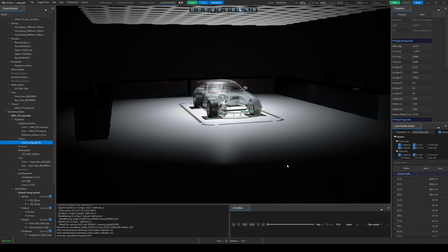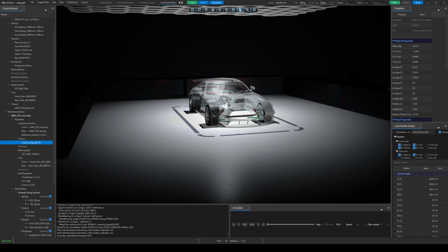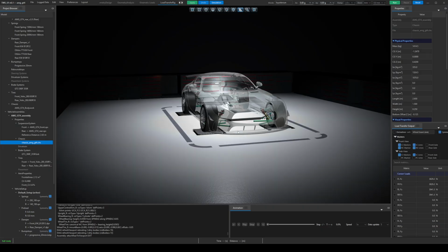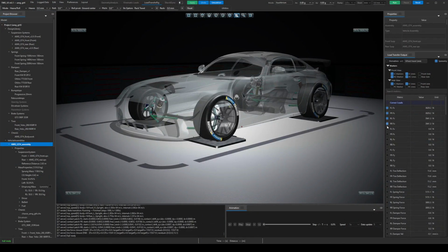The basic idea is simple. External accelerations are applied to the model using D'Alembert's principle. So instead of simulating the full vehicle motion around a track, the logged or prescribed acceleration field is applied to the multi-body model as equivalent inertial loading. The model also uses a special rig tire.